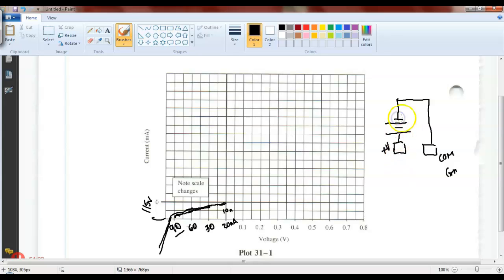So that means the long one points there. It's variable. So your circuit's going to come out, and you're going to put the 300 ohm resistor. You're going to put the 1N914 with the cathode pointing toward the positive, and then this right here will come back and go to your common. So that'll be your circuit. Everybody okay on the trainer now, right? Any questions on this?